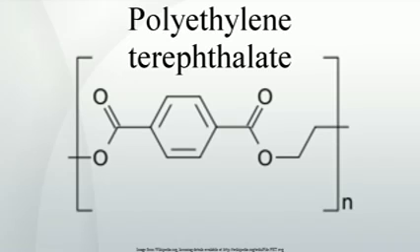About 60% crystallization is the upper limit for commercial products, with the exception of polyester fibers. Clear products can be produced by rapidly cooling molten polymer below Tg, the glass transition temperature, to form an amorphous solid. Like glass, amorphous PET forms when its molecules are not given enough time to arrange themselves in an orderly, crystalline fashion as the melt is cooled.